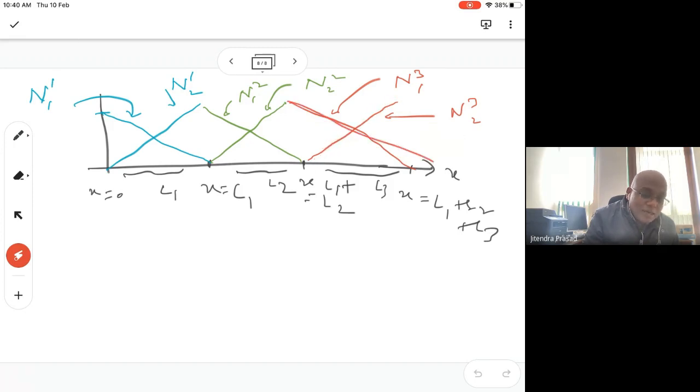So automatically this interpolates between u3 and u4. Got it? Our formulation of the trial function itself is such that it automatically interpolates between the nodal displacements.